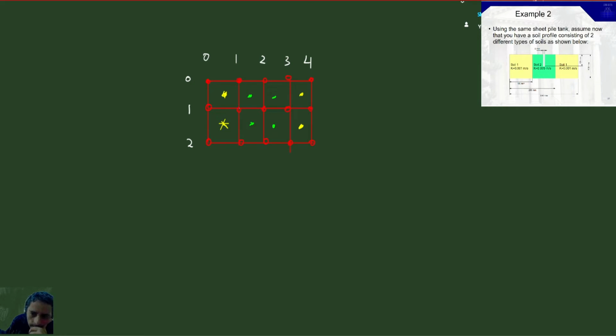I want to calculate kx for this node, like when I want to calculate the head at that node looking at the neighbors. So I have to look at the two neighboring nodes, which are this one and that one, correct? So where should I calculate the hydraulic conductivity? Well, for kx, I have to calculate the hydraulic conductivity at the edge of two elements, which could be two different materials, right? This material and this material could be different.